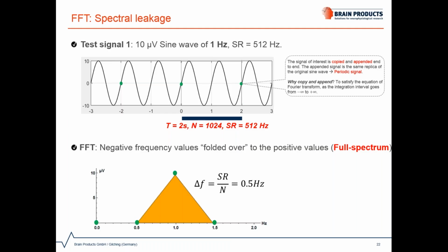Since the frequency content of our sine wave was 1 Hz, as expected, we have confirmed with the help of FFT the frequency spectrum to be exactly at 1 Hz and 0 at the adjacent frequencies. In other words, if the input signal has a frequency which is an integer multiple of the frequency resolution, then the entire energy will hit the bullseye at exactly 1 frequency bin, and the remaining frequency bins will have 0 energy. As you can see in our example, 1 is an integer multiple of 0.5, and that proves why we get the exact peak value.